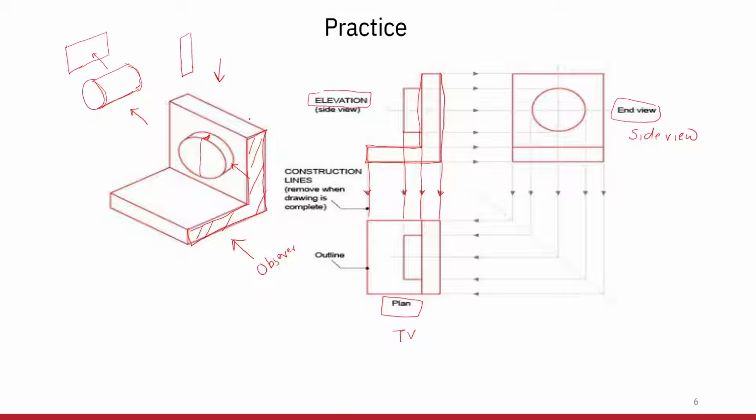Now once we have taken the projections, we need to know how much the length is while looking in this direction, right? So we will mark this edge like this. Then following this projection, we will mark this line which is equal to the length of this object, correct? Then this cylindrical portion will also be observed as a rectangle in the top view. So for that projection, we will mark this. Now we need to understand that this object is symmetrical in the top view, right?